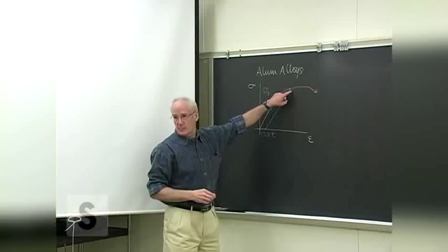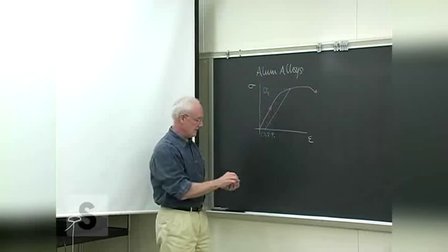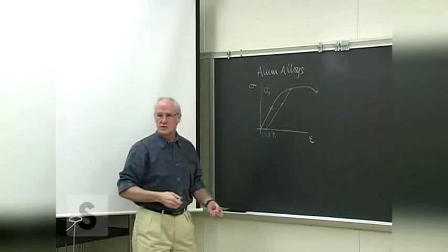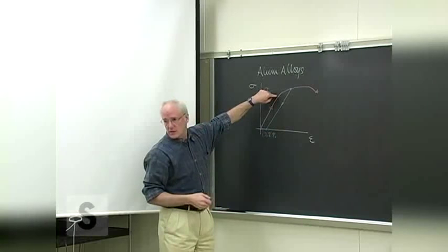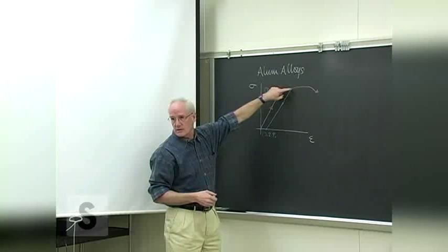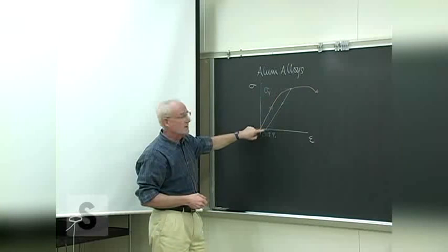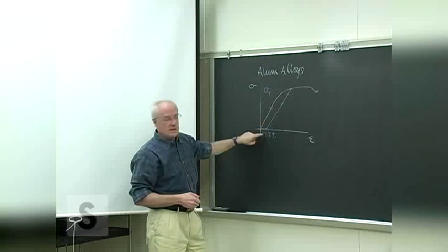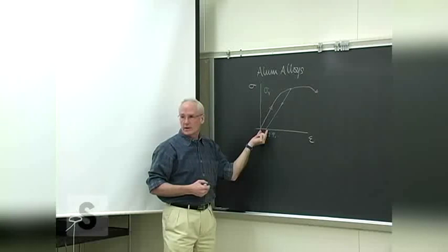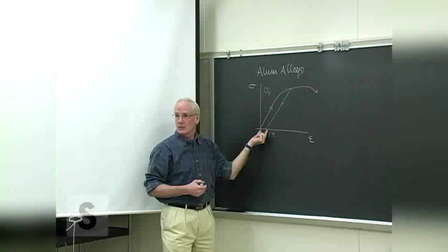If it gets to this point and the load is relieved, it tends to come down this line. Once you've gone past the true linear region up into the curve somewhere, if you relieve the load at that time, you'll come down this line to a point where the load is completely removed, but some residual strain remains.